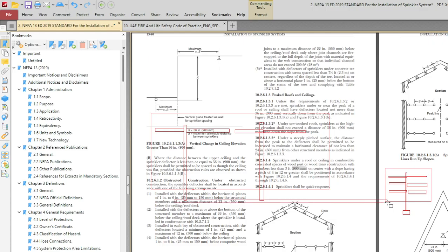Okay. Now another one. Remember that area: how much area can I cover for one zone? 4,830 square meters will be connected with one zone control valve. Yeah. Okay, and also one alarm check valve. If you have an alarm check valve, that is sufficient for this particular zone. But this zone control valve, what is the purpose? When you have multiple zones, multiple floors, it is to identify in which zone you have a fire. Clear, right? Yeah, clear.